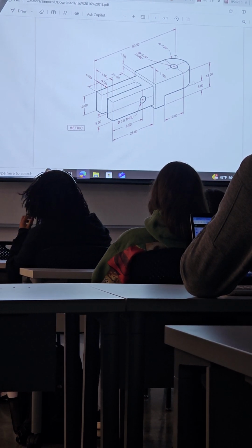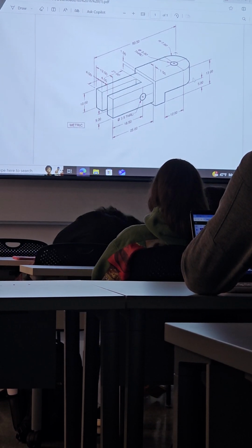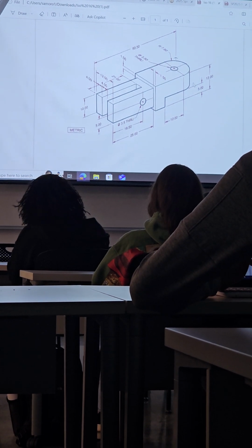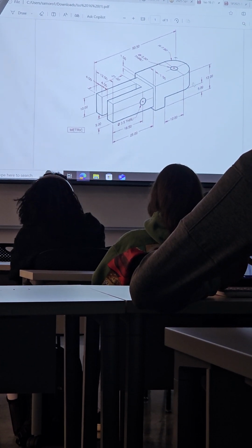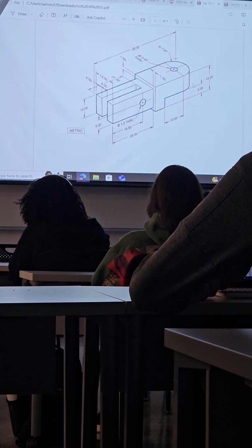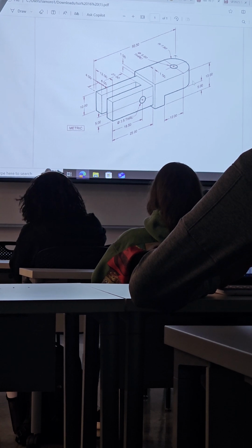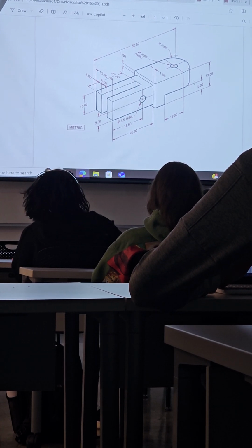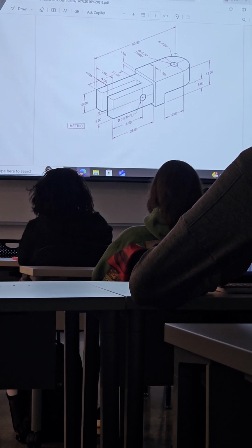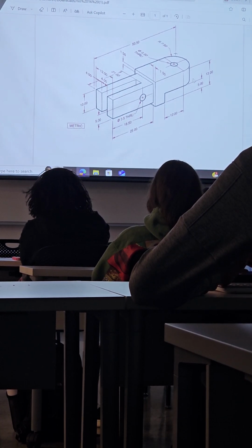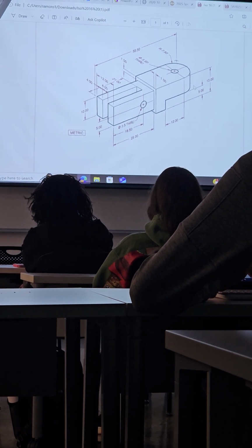One of the reasons too for double dimensioning is if there's rounding errors, you can have 2 dimensions that don't add up to the total. So you want to make sure you leave a little bit of room, and it also just increases the opportunities for errors. So for example, if you're drawing something by hand and you don't have automatic dimensions given to you from AutoCAD, you just have more places to make errors. So it's considered bad form to double dimension.